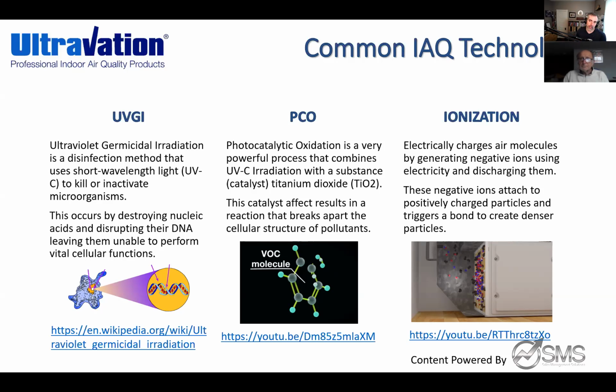This is becoming more and more popular in the past couple of years. There are some people who are so sensitive to the ozone smell, a very, very small part of the population, that they say, hey, I don't want to do UV at all. I said, okay. So we have what's called ionization. Ionization, long story short, is electrically charging the molecules in the air. They figured out how to replicate a lightning bolt going across the sky. It basically creates an electronically charged field. We have a device, an ion generator, that creates the ionization. It negatively and positively charges the dirt molecules in the air and helps them stick together.